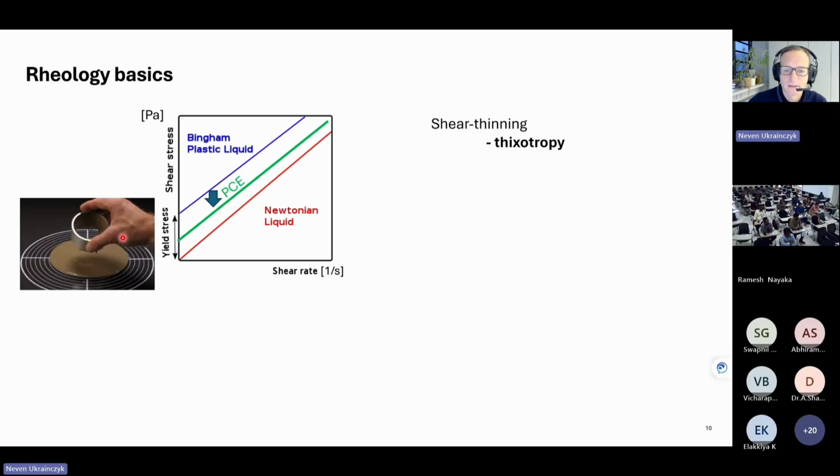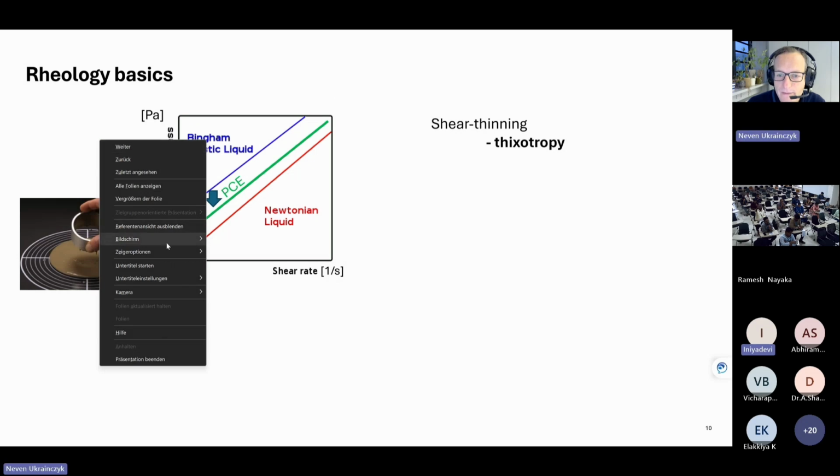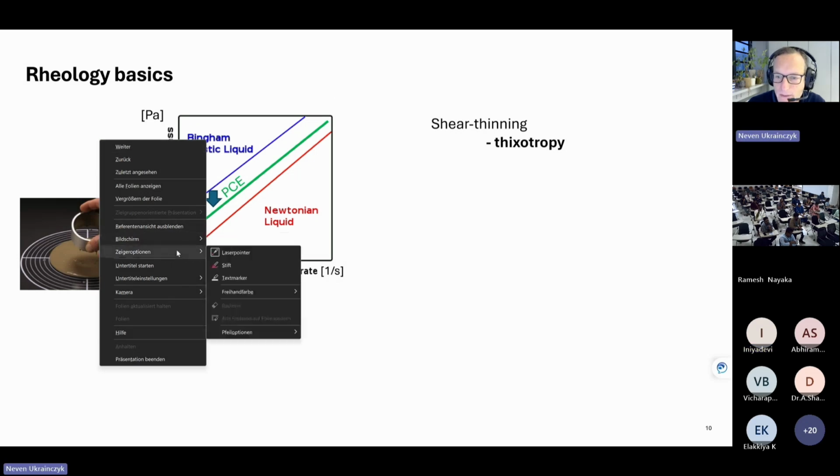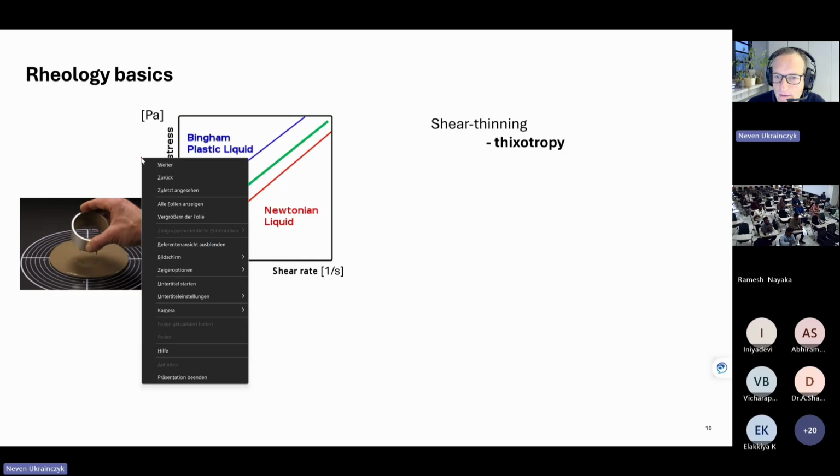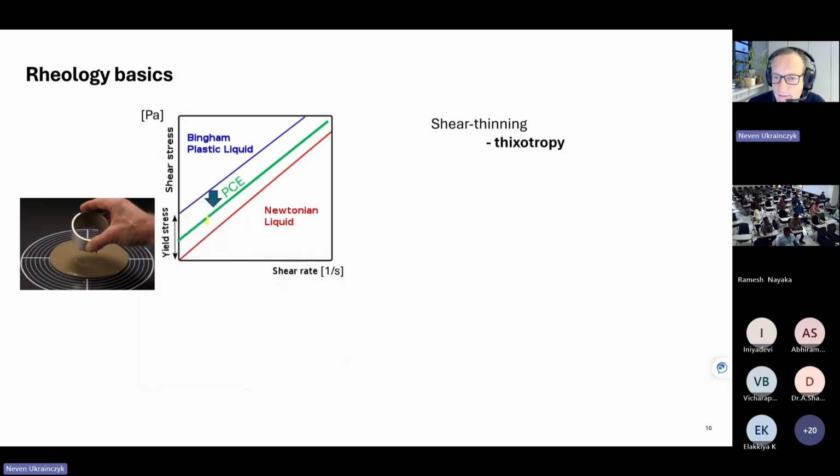And we actually also measure this by the slump flow. This would be just the typical behavior, but we also have, I will try to draw this, maybe with a bit thicker line, shear thinning. That's the thixotropy, and cement paste is shear thinning, and also what I mentioned before, ketchup.